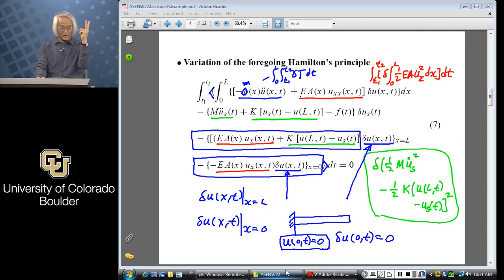There are 2 boundary conditions, right? One is essential, one is natural. Or one is kinematic, the other is a von Neumann boundary. One is a Dirichlet boundary condition or von Neumann boundary condition. I don't know what phrase you are instructed to use. Dirichlet and von Neumann? Okay. So this is Dirichlet or von Neumann? Dirichlet. Okay, this is essential boundary condition. Essential means kinematics. So when you identify boundary condition, you look at kinematics first, geometry. When you cannot find the boundary condition from geometry, that's when it becomes a von Neumann boundary condition or a natural boundary condition.